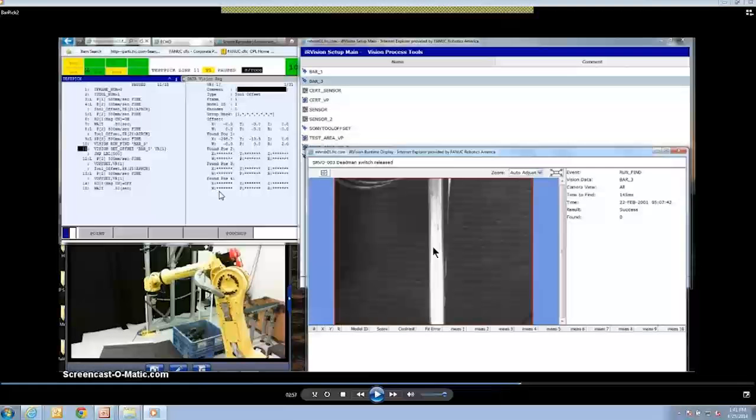So in this case, it just crapped out because it didn't have any label 500. A couple of different things you could do. You could have a larger field of view, depending on the application, how far off the part's going to be. You could even do some kind of histogram and decide, oh, it's too far in the field of view, let me automatically move back.